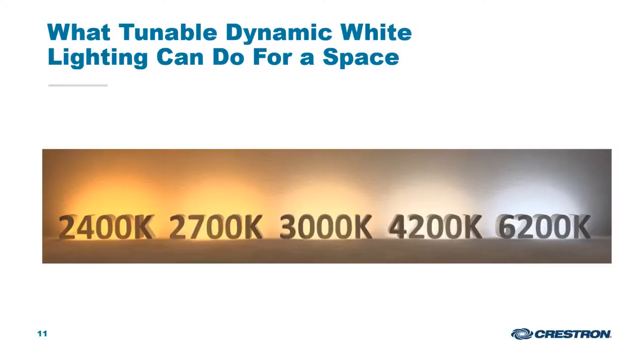White light has typically been referred to as either warm or cool, daylight, bright white, or soft white. These names correlate with specific color temperatures of white light and describe how the light is perceived. CCT, correlated color temperature, as the term suggests, refers to the color temperature of light, measured in degrees Kelvin. Within the lighting industry, it's typical to see white LEDs created anywhere between 1800 Kelvin, candlelight, and 7000 Kelvin, daylight.